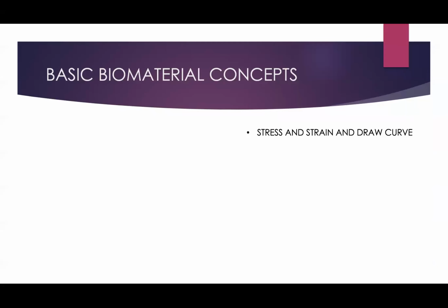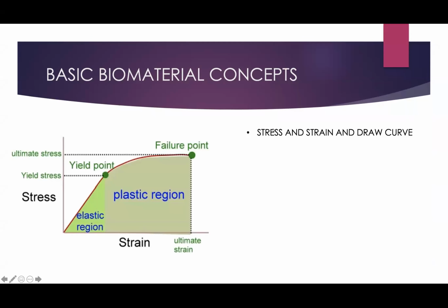way, which is known as a stress-strain curve. And you need to be able to draw one of these in the exam. So stress is basically force per unit area, whereas strain is change in length divided by the original length, and it has no units.